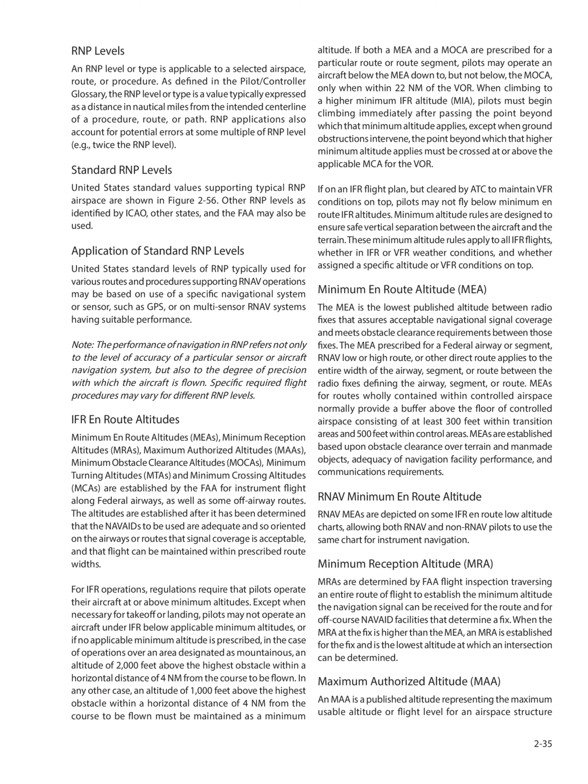Minimum altitude rules are designed to ensure safe vertical separation between the aircraft and the terrain. These minimum altitude rules apply to all IFR flights, whether in IFR or VFR weather conditions, and whether assigned a specific altitude or VFR conditions on top. Minimum en route altitude, MEA.